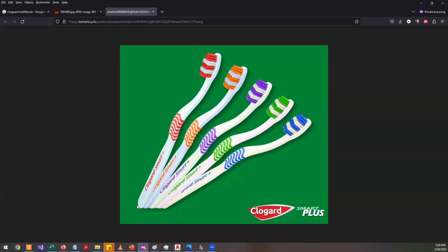You may be wondering whether, since you know about the loft command, you should use loft to model this one. Yes, you can use loft, but loft is too difficult because you need cross sections in every location and you need a proper guide curve. Not one, but multiple guide curves to guide these cross sections along the path you need.